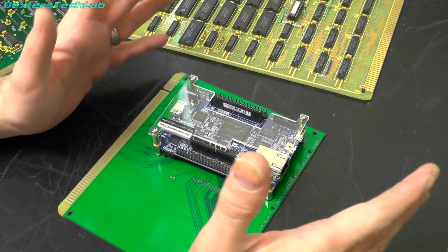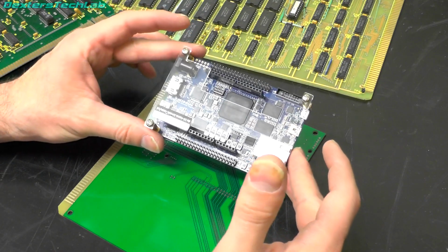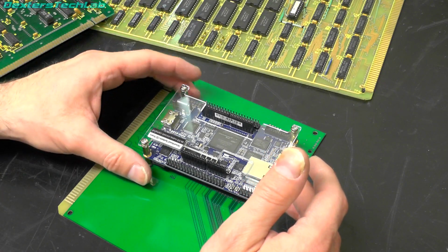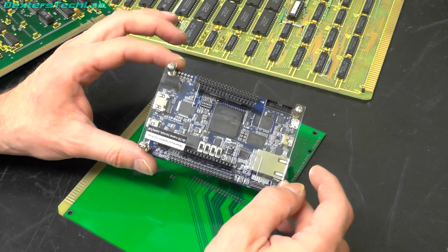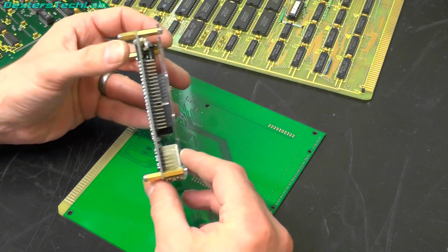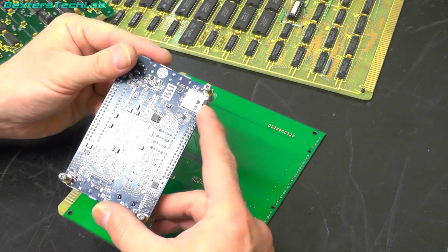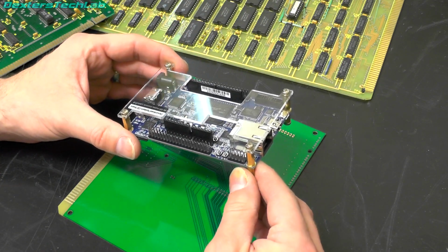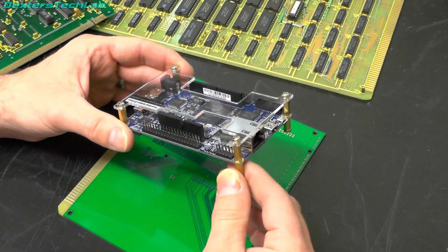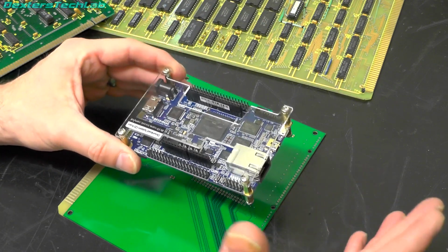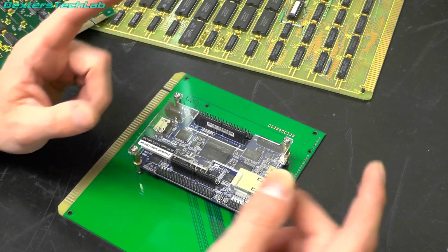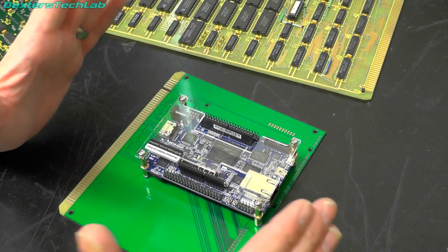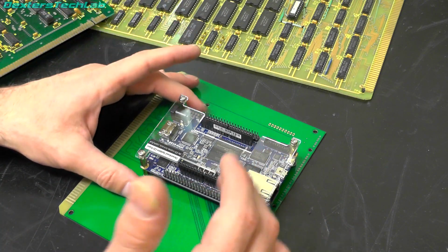The way that we're hoping this is going to work is this will use the signaling that comes out of the disk sequencer card to select a track of data that's located probably on the micro SD card that's already in here. It will probably use the same sync byte that the disk sequencer is actually looking for, because we can use that to pick out what is actual data as the DPB is writing to the disk, and then write that, just the data, into an array on the SD card.